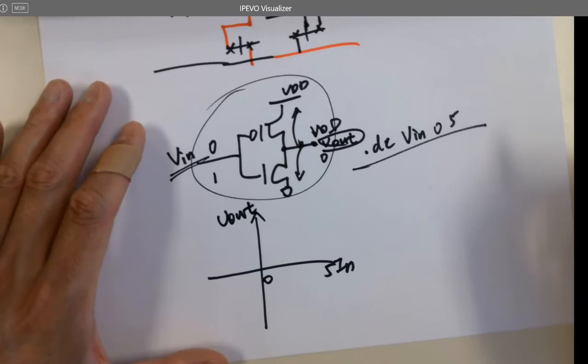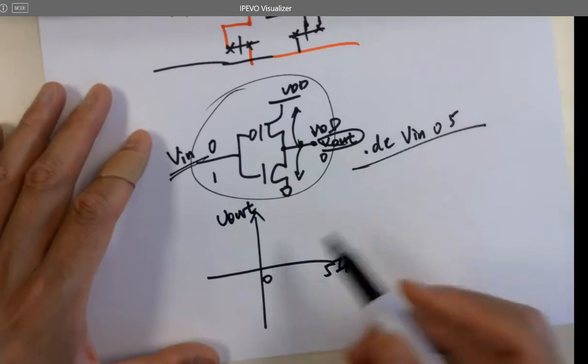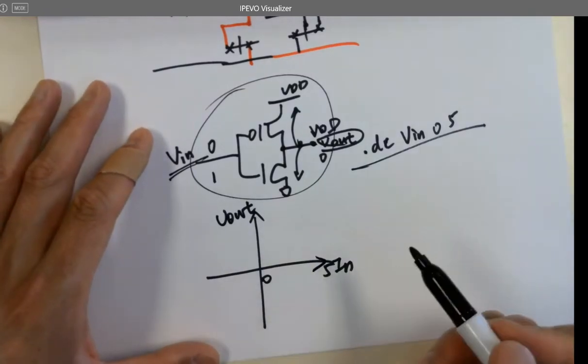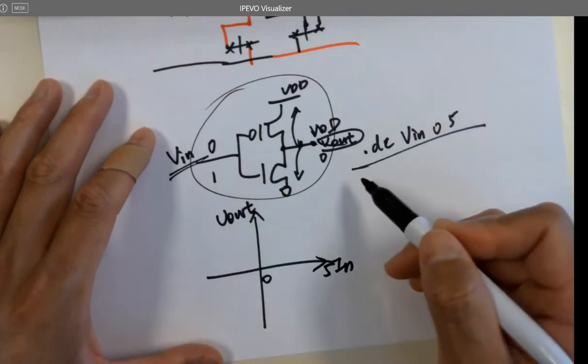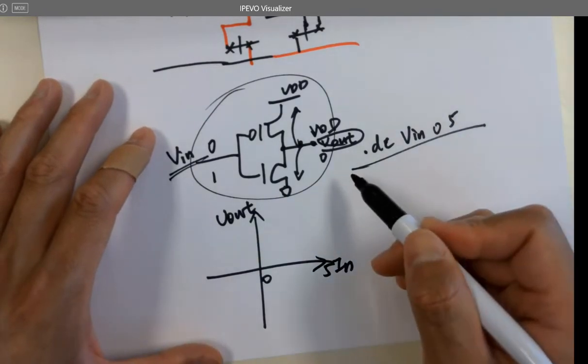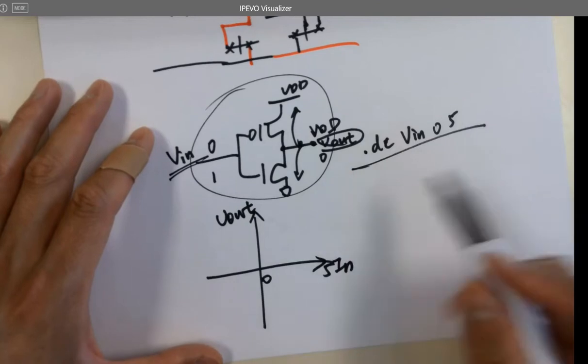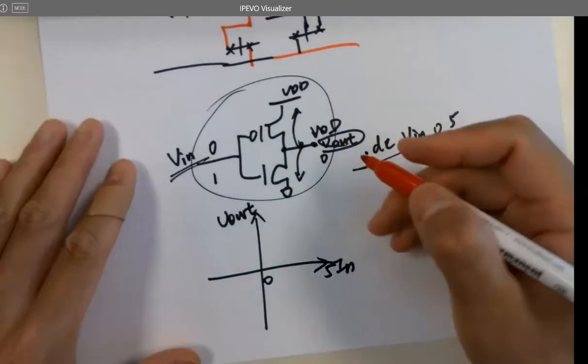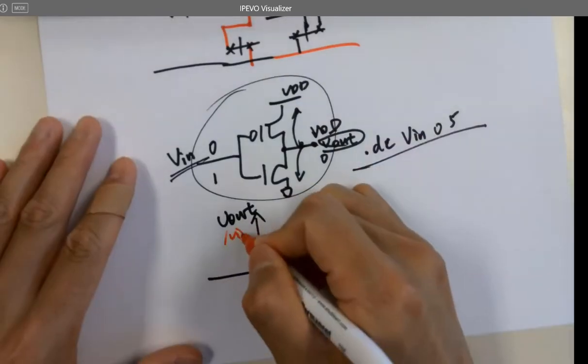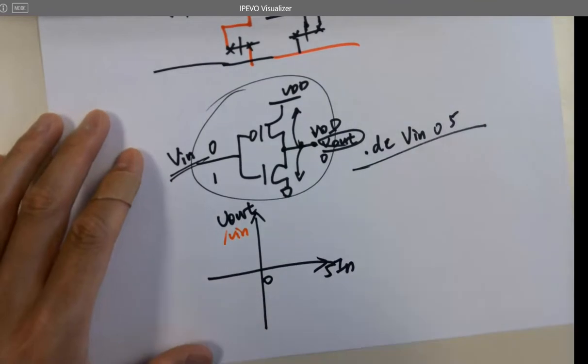No, I don't think that would be linear. So, for example, you are doing a DC sweep for V in, but can you plot V in here as well? The x-axis is V in, but I can still plot V in. It can be V out, can be V in. I'm just plotting whatever you want to plot. It's probe, double click.